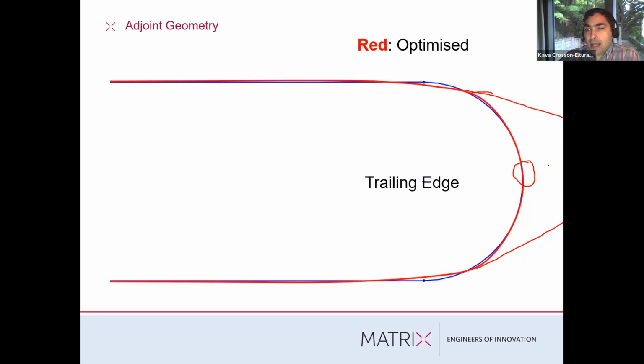And you might see that as a bit of a benefit depending on your application. So it seems to me like the best application for this tech would be either early on in the design cycle where you've got a lot of freedom, or even later on where you've got existing structure that you want to make incremental improvements to. Small aerodynamic features are going to be easier to add to your design just because they interfere less with surrounding structure or internal structure. So, yeah.